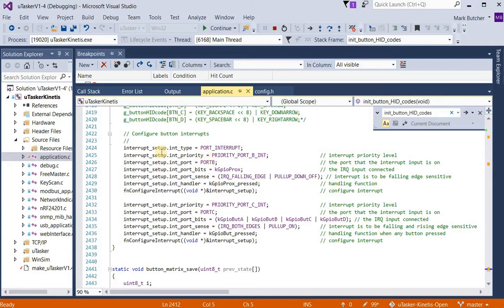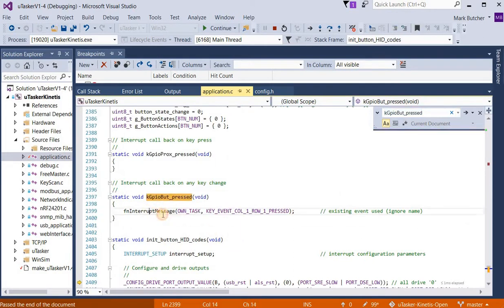The code below is doing the interrupt configuration. This is the only one of interest here. I'm configuring on port C 4 interrupt inputs which will all cause the same interrupt handler to be executed, and I've set this up so that any changes, either positive or negative edges, will cause this to happen. This will avoid any polling, so I'm going to put a breakpoint also on this line so that we can see the interrupt taking place, and I'll let it run.